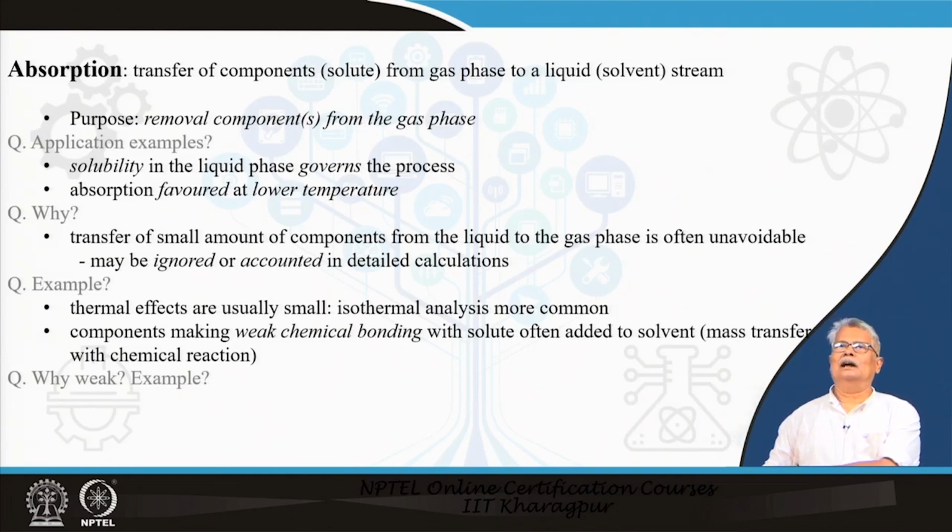What can I do? I can bring in a solvent which is alkaline in contact with this particular gas phase which contains the carbon dioxide, and if an alkanolamine component in the liquid phase is used, it will be absorbing the carbon dioxide from the gas phase to the liquid phase. This is a typical example.